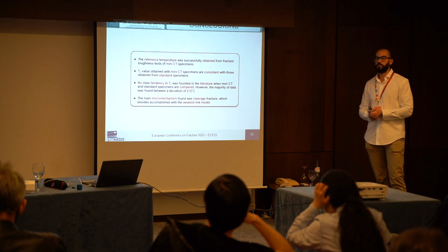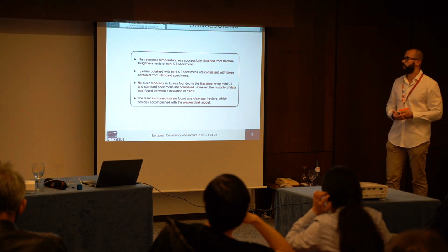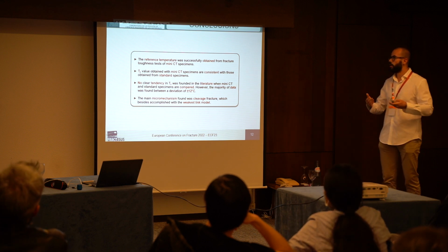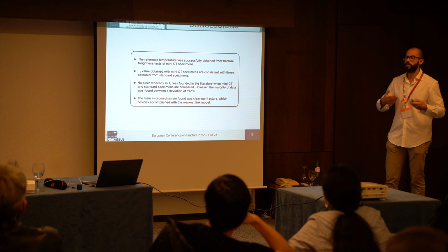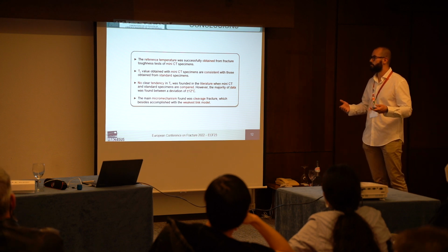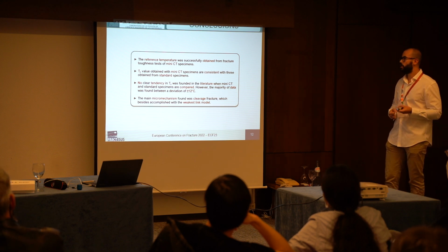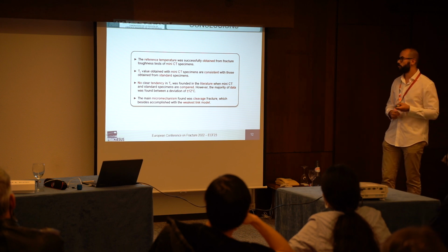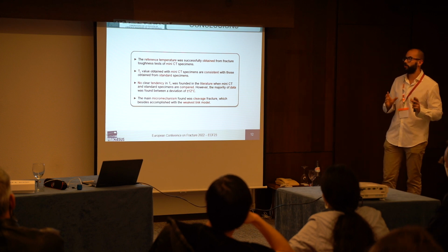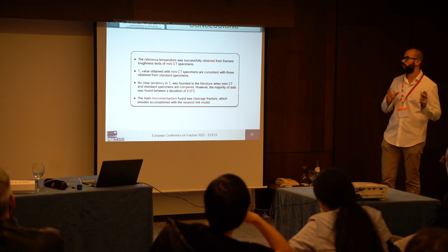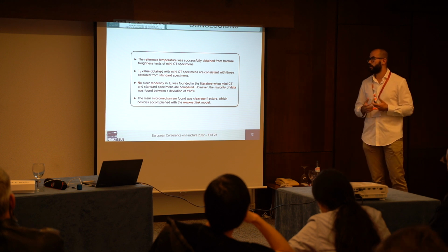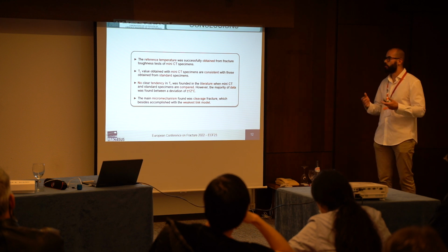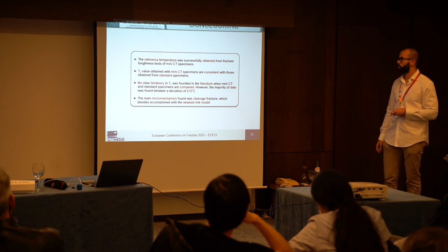With all this, the conclusions are: the reference temperature was successfully obtained from fracture toughness tests with limited specimens. The T0 value obtained with the mini-CT specimens is consistent with those obtained from standard specimens. No clear tendency was found in the literature when mini-CT and standard specimens are compared. However, the majority of data was found within a deviation of plus minus 12 degrees. The main micromechanism found was cleavage fracture, which is also consistent with the weakest link model.